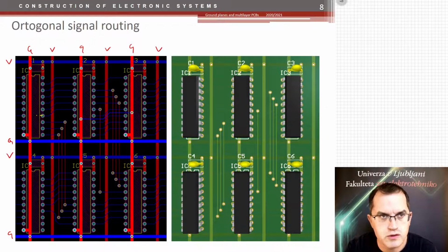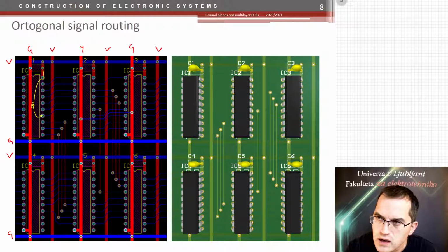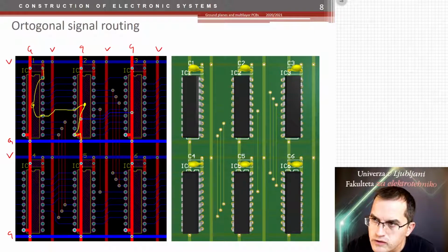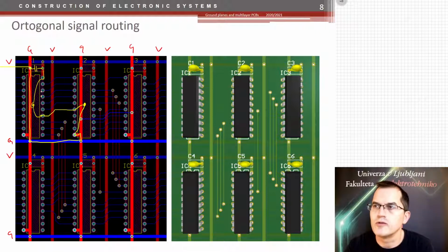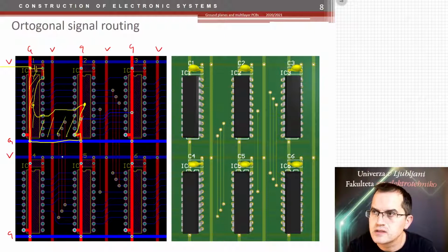So if I want to make logic 1 on that point, I would take current from the power supply, then it will go into the circuit and then run to this line here. Then it will go inside the chip and then go to the ground and here and return back to my original capacitor. So this is a high frequency loop formed because of that single track.